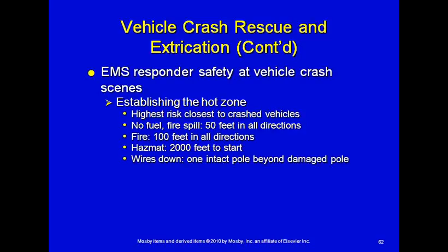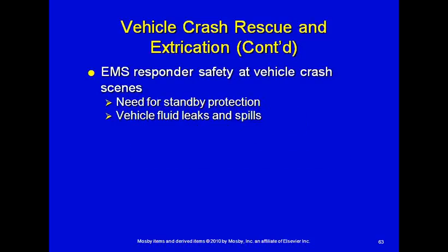If you've got wires down, look at the pole beyond the damaged pole and see if it's upright, intact, if the wires are attached to it, because that may be an indication that you're dealing with a live line.